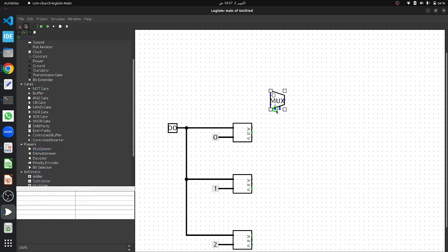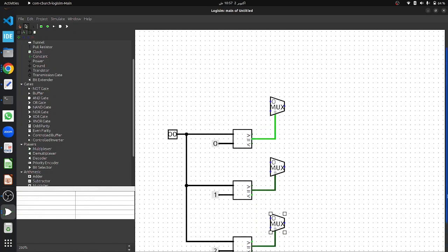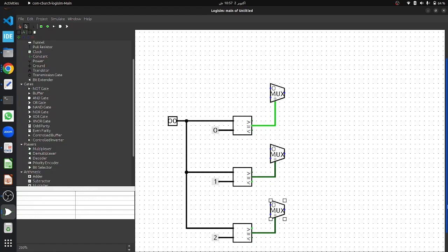Alright, so just disable this enable signal for now, and I'm going to connect this equal sign here, using another multiplexer, connecting this. I'm not changing the data bits right now so that we don't have to change them again and again. So this is our logic here, and now I'm going to OR all of these 3 muxes, because for the current moment I just want the ALUOp, either it may be 0, it may be 1, or it may be 2, right?